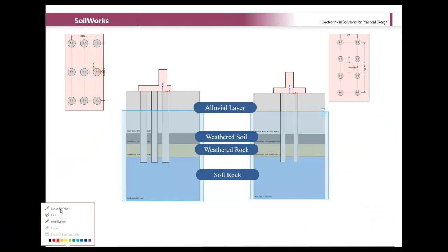So basically we have modeled the pile and the foundation underneath. We had chosen two different lengths, that is 13 meters and 10 meters. Likewise, you can go for 12 meters, 10 meters, or 9 meters as well, so that based on the results we can find an optimistic result, and proceed to analysis and design in the structural software. Similarly, you can do a number of sections and parametric studies.